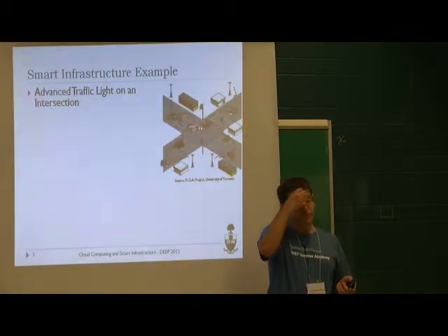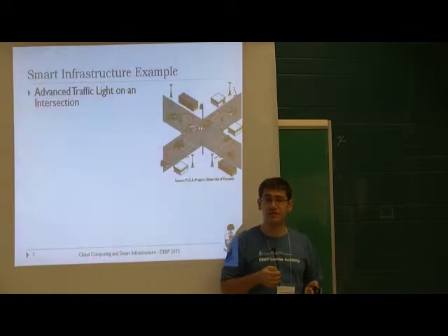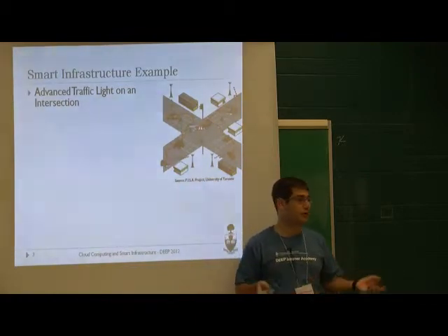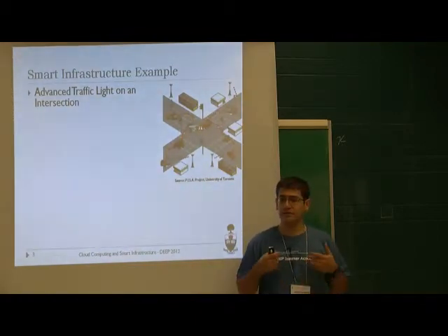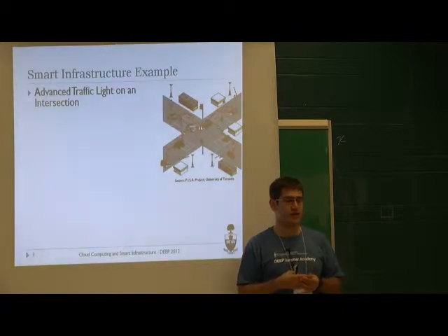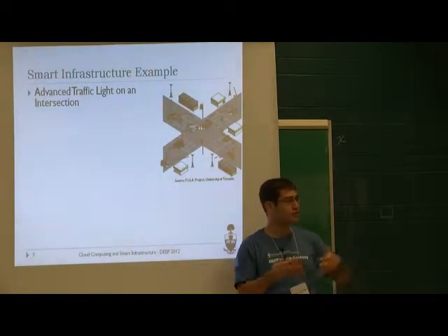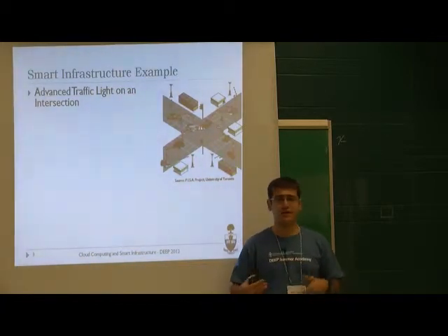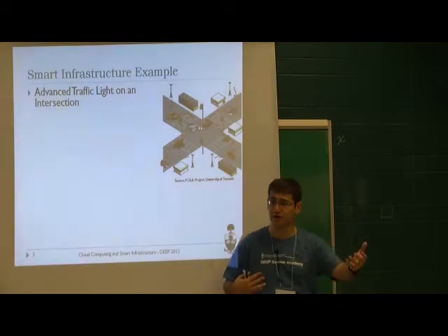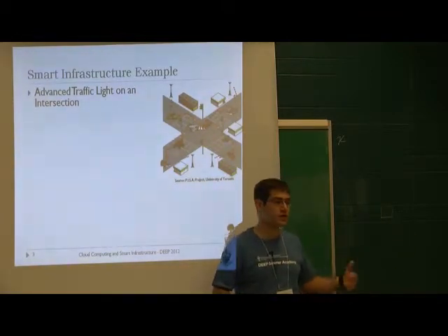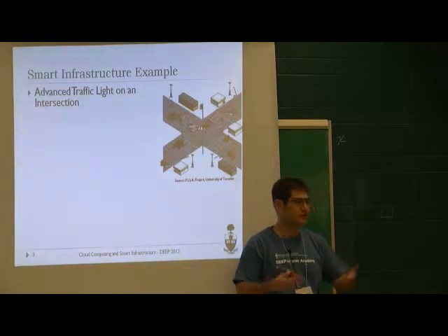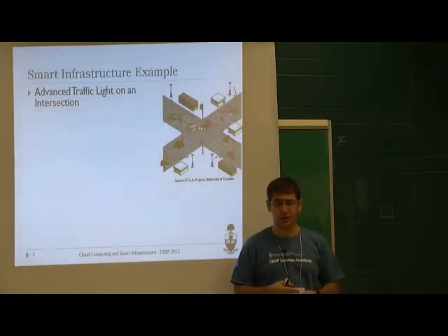Okay, so push buttons are used for pedestrians on local roads, and usually you have a major road and a more minor road. The major road has a longer green time, while people on the minor road will have to wait more because there are not enough vehicles that actually use that road a lot.